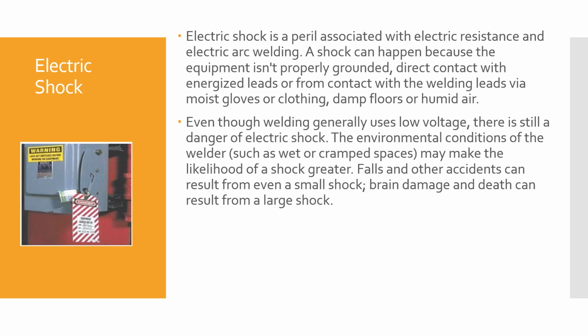Electric shock. Electric shock is a peril associated with electrical resistance and electric arc welding. A shock can happen because the equipment isn't properly grounded, from direct contact with energized leads, or from contact with the welding leads via moist gloves or clothing, damp floors, or humid air. Even though welding generally uses low voltage, there's still a danger of electric shock. The environmental conditions of the welder, such as wet or cramped spaces, may make the likelihood of shock greater.